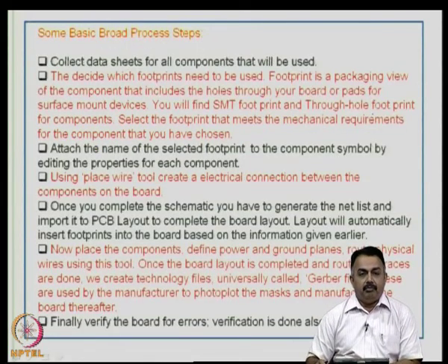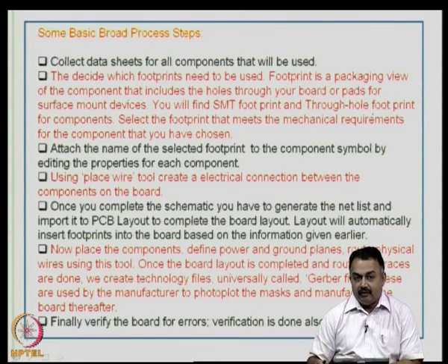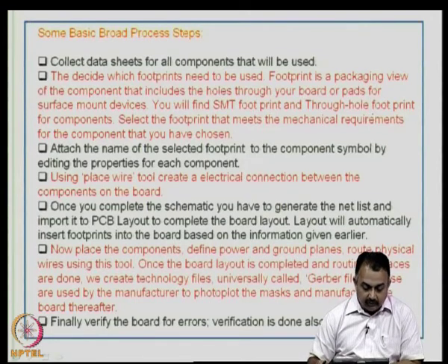Now, let us look at the broad process steps in a work environment, or when you start with a circuit design. What are the things that you will do? Collect data sheets for all components that will be used, clear. Then you decide which footprints need to be used.